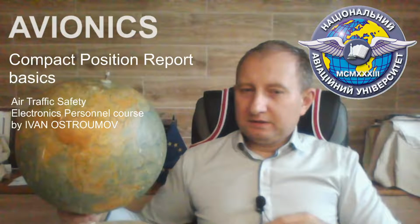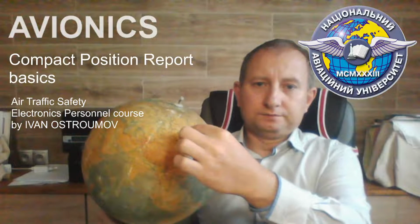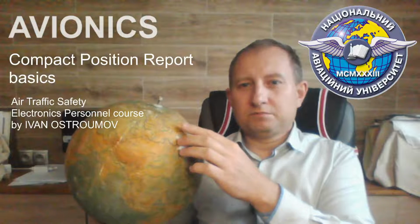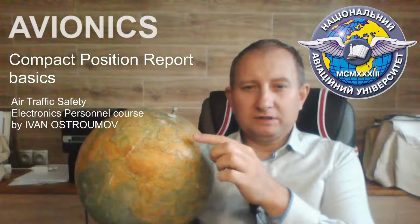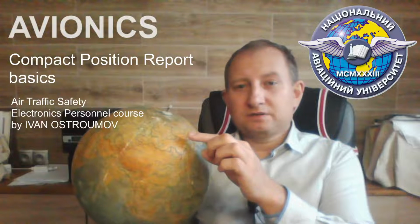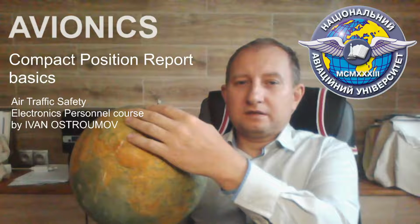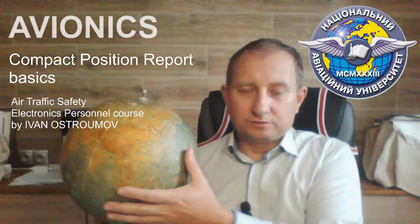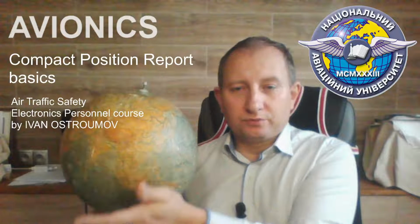It is a good idea to localize a small rectangle where we are, mount a small reference frame, and count our coordinates within this small reference frame. It gives us a huge advantage because we do not need to store the data on the global scale of latitude and longitude. Why? Because we do not need it during one movement of the vehicle.